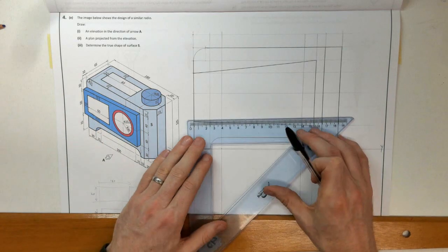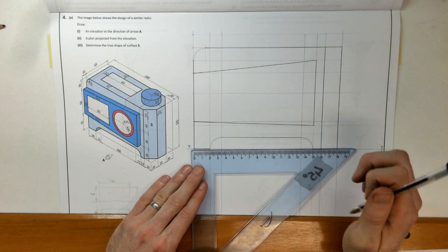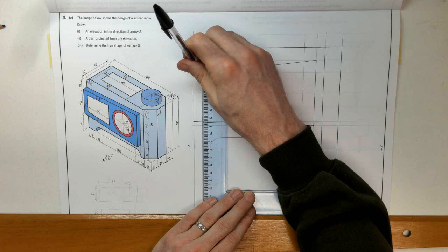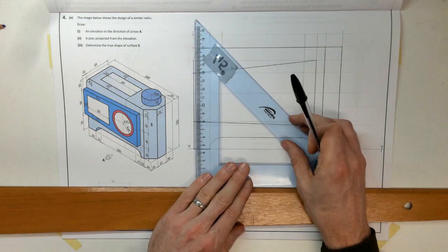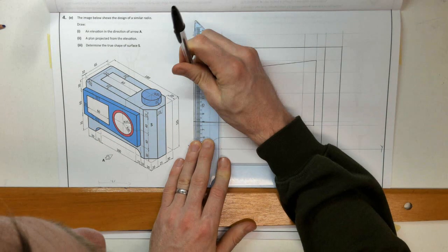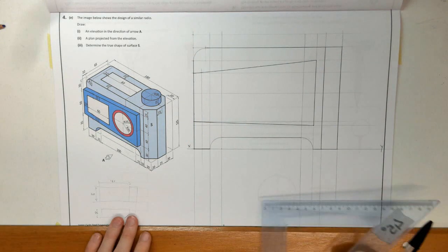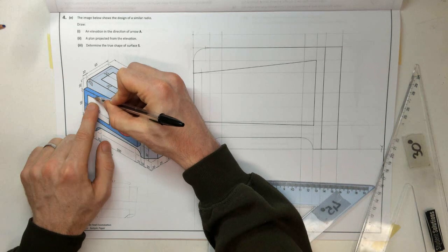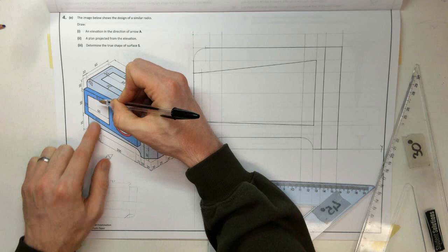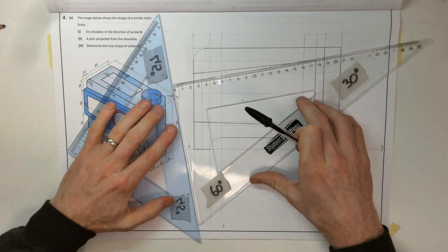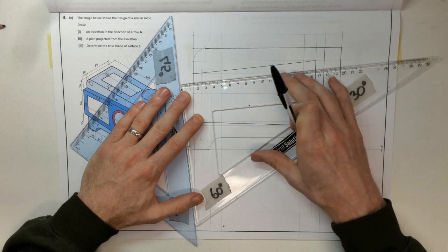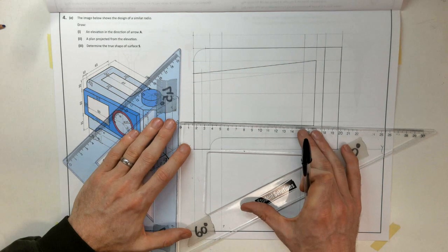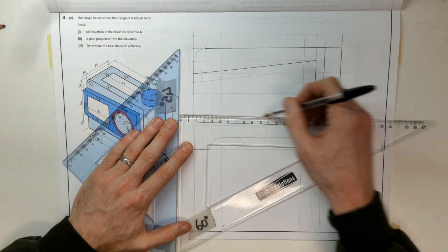At my little screen, they're telling me it's in 10 millimeters. I'll draw my line vertically up, and I've got a distance of 10 there that I need to mark vertically, and another distance of 10. So I'm going to mark them off there and there. And we can see that that and that are parallel. There's just a little symbol to show that that edge and that edge are parallel, and the same down here, parallel and parallel. So sliding set squares parallel to this edge, just draw that, extend it on, and parallel to this edge, draw that extending there.